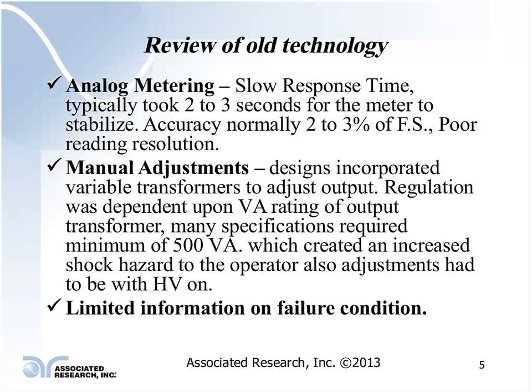So the short circuit current of that instrument is specified typically as 200 milliamps short circuit, and most testers are able to supply much, much more than that under a short circuit condition. So it creates a hazard to the operator. If the operator makes a mistake, it could be lethal.